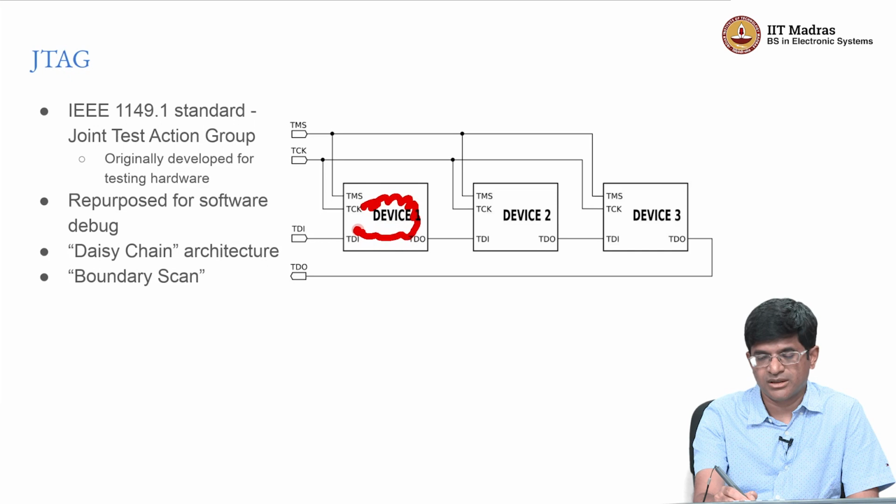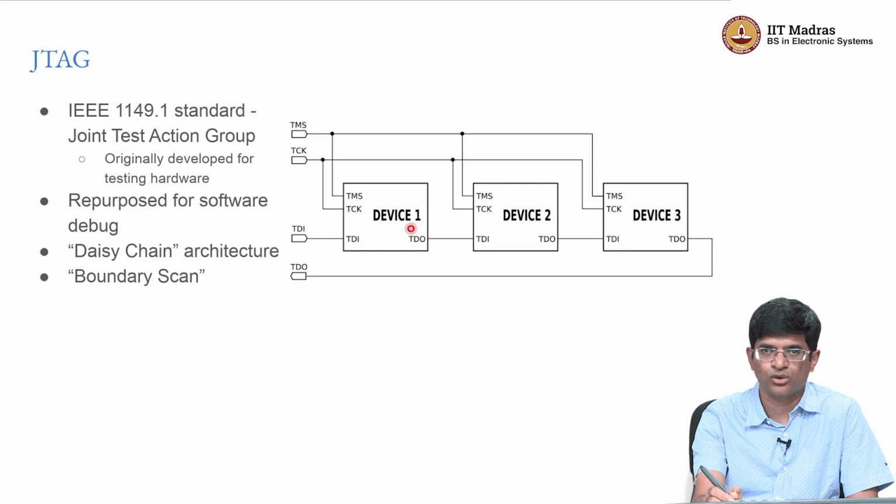The only normal way that we would think of would be that I need to actually take wires out for each and every one of those registers, but that's impractical because of the number of registers inside each individual device, right? You are probably going to have thousands of bits on average. It could be in the millions, and you simply don't have that many pins that you can take out of each device. And even if you somehow manage to get, let's say, 1000 pins out, you don't have an easy way of coordinating, okay, 1000 from here, 1000 from here, 1000 from here, how do I collate all of them and get something useful out of that?